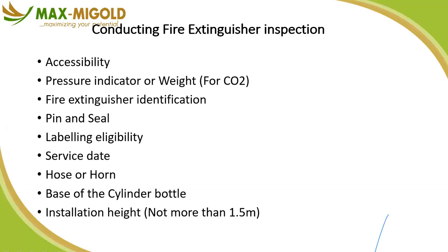And if that has been done, you need to then identify that extinguisher either by location or just by numerical identification. So if I have FE standing for fire extinguisher 01. Let's assume that we have less than 100 in that facility, then we can start the numbering from 01.